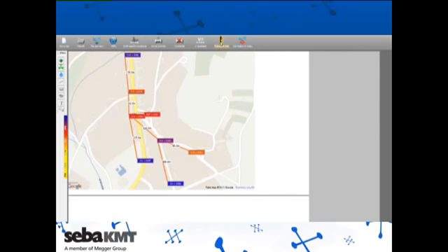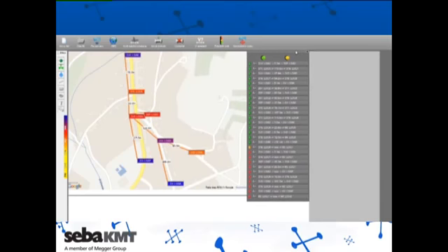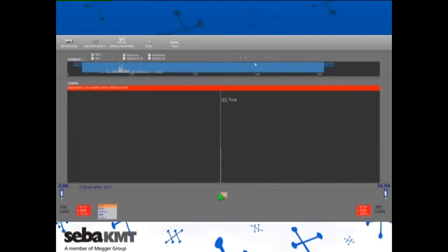We see the distance of the leak from both sensors and, at the top, the coherence curve with the option of frequency adjustment. After activating the Show Leak function, we obtain a traffic light display of all correlation results right in the map view. By clicking on the drop symbol in the case of this result, the calculated leak location is indicated on the map as a drop. By clicking on the correlation symbol, we end up back in the detailed view of the correlation result.